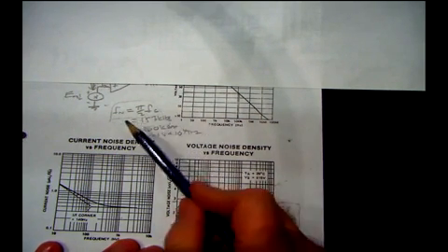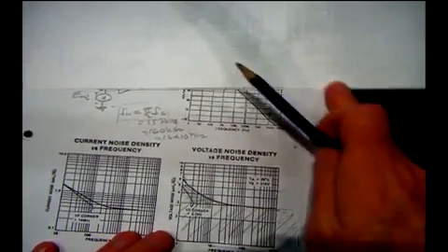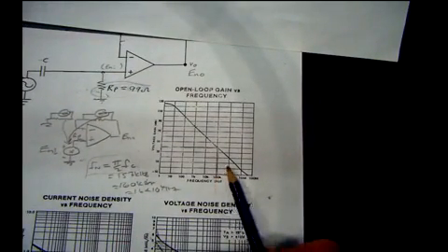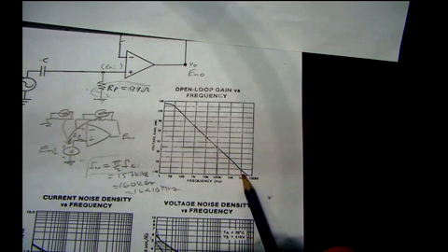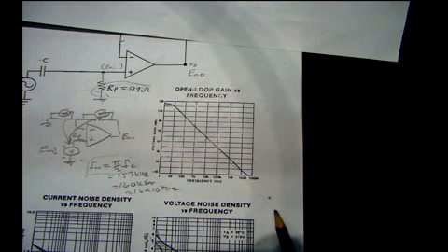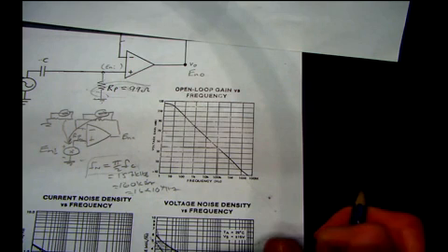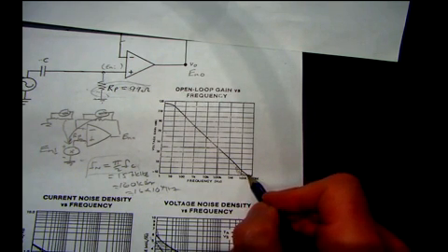frequency. This is the idea, the concept of a noise integral, which is to say, even past the signal bandwidth here, any noise is still going to get amplified progressively by less and less with frequency. So the thought experiment here is to say, okay, we'll have a lot of stuff coming through and that'll be amplified.